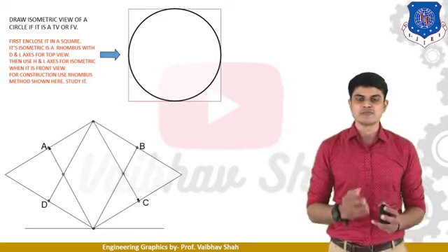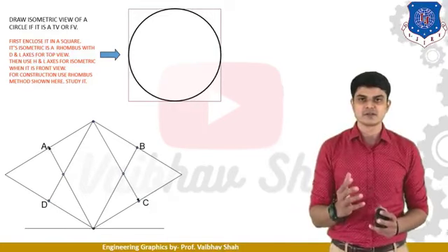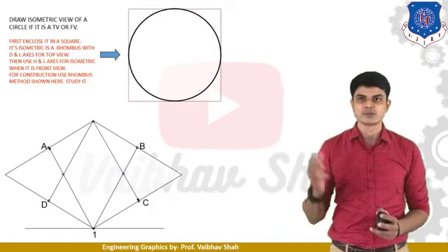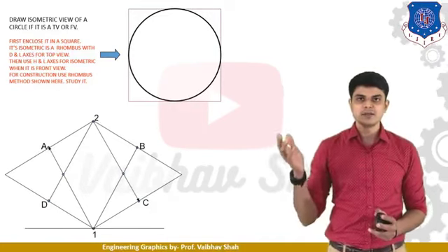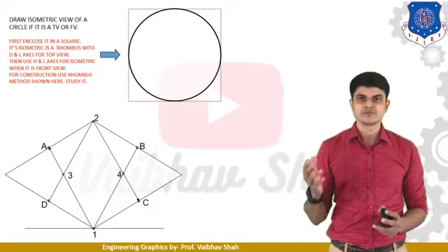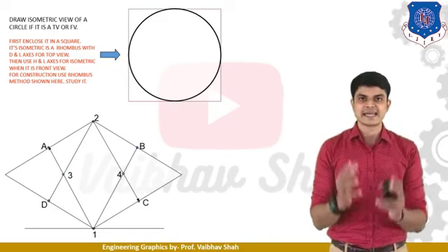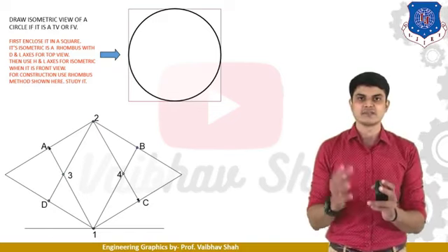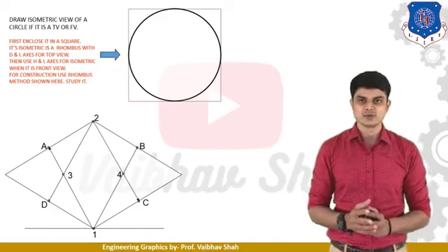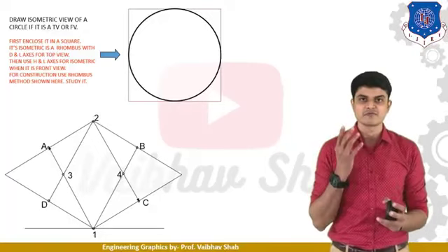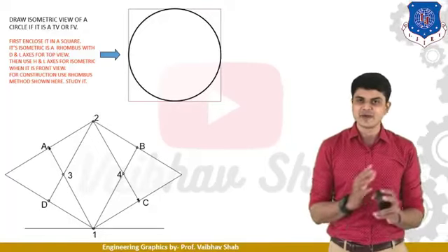So we will have a total of four centers generated. Let us observe the four centers: 1, 2, 3 and 4. The first two points are at the endpoints of the shortest diagonal, and the second two points are at the intersection of these cross-intersecting lines. Very easy, so we have found our four points. Now the next task is very simple.